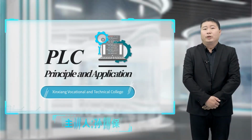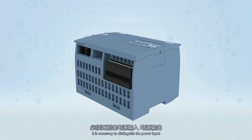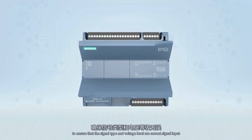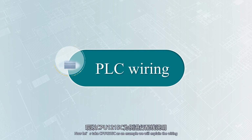Hello everyone. There are many CPU specifications for S7-1200 PLC and their wiring methods are similar. It is necessary to distinguish the power input, power output, signal input, and output wiring terminals to ensure that the signal type and voltage level are correct. Now, let's take CPU 1215C as an example. We will explain the wiring.